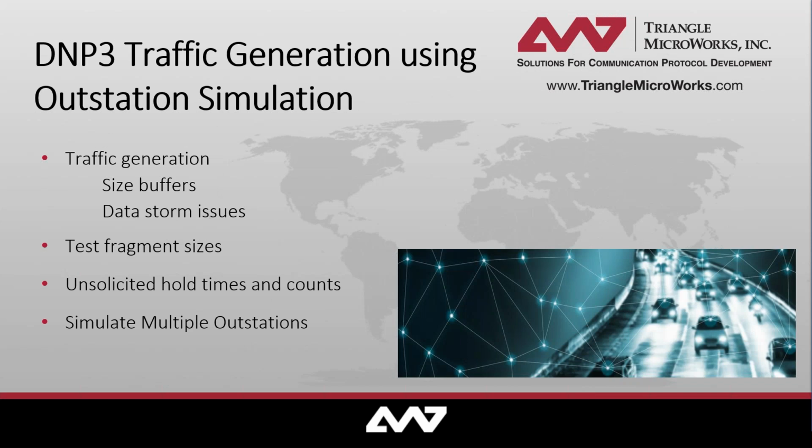So now let's talk about simulating an outstation in Test Harness. You may want to simulate DNP3 outstation traffic for multiple reasons. One reason is to test large volumes of messages being propagated in your system to test your master device under a heavy load. You can test performance of your master device, how it will respond to large buffer sizes, or even overloads. You can also generate data from a single or multiple outstations.